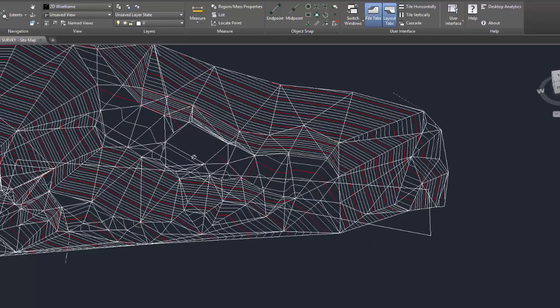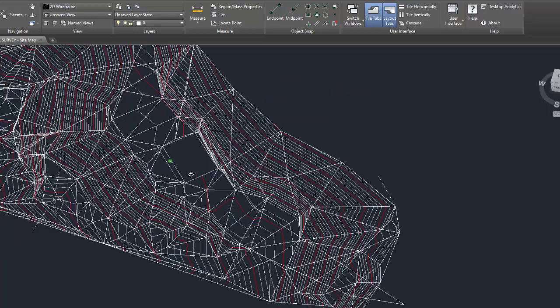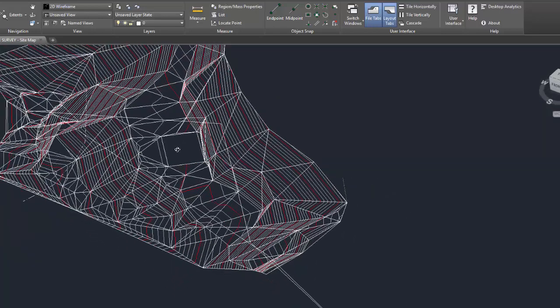So Traverse PC excluded those triangles from the polyface mesh, and that's exactly what I wanted it to do. I didn't want there to be any triangles there in the CAD file. So those triangles that are invisible in Traverse PC export directly over to invisible faces in the polyface mesh inside of CAD. And the same thing would happen if I send out a LandXML file. When I open the surface from that LandXML file from Traverse PC, those triangles will be excluded there as well. So Traverse PC's exclusions work directly with CAD exclusions and LandXML exclusions.